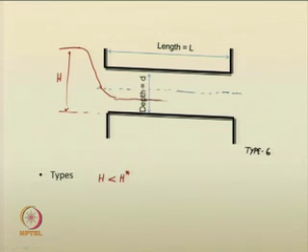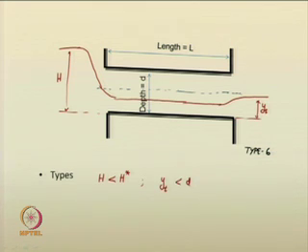The flow inside the culvert barrel is supercritical, and it may just rise a little bit to YT. Okay. So, what does this mean here? So, YT is less than D, that you are quite aware. YT is also less than YC.